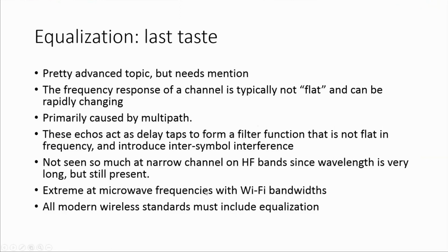All wireless standards include equalization of some sort or a way to deal with multipath. What are the bandwidths at Wi-Fi? 802.11 has 6 or 8 different modulations, but more or less everything is about 20 megahertz because it's OFDM.